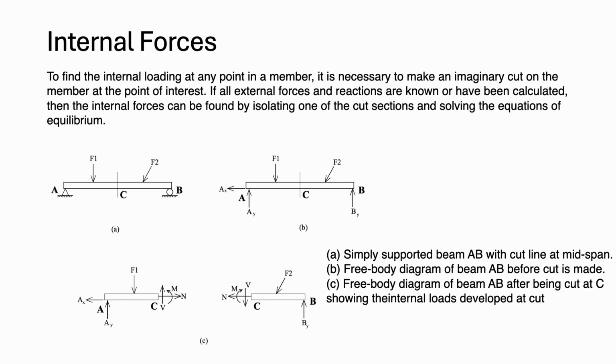So the next are internal forces. In order to find the internal loading at any point in a member, it is necessary to make an imaginary cut on the member at the point of interest. If all external forces and reactions are known or have been calculated, then the internal forces can be found by isolating one of the cut sections and solving the equations of equilibrium.